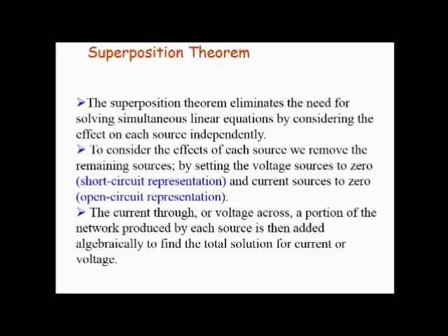Now the next theorem is the superposition theorem. This superposition theorem holds the same for AC circuits as we have studied in DC circuits. The superposition theorem eliminates the need for solving simultaneous linear equations by considering the effect of each source independently. That means we will consider the effect of each source independently, and afterwards we will combine the effects to get the net resultant. To consider the effects of each source, we remove the remaining sources by setting